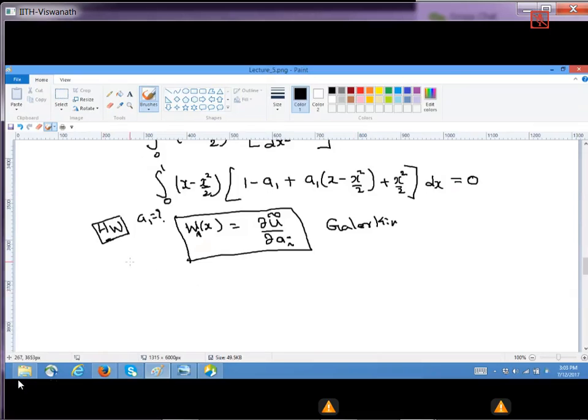One has to note at this point that the Galerkin method is the modern method. The modern finite element has evolved from the Galerkin methods. You will see that this will automatically determine some kind of psi function, which is nothing but your shape functions, also determined through the same psi i. So the modern finite element has its heavy roots in the Galerkin method. With this we will end the Galerkin method, and then the last method I would suggest.